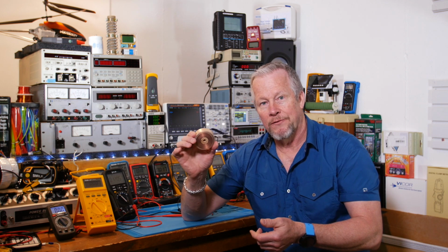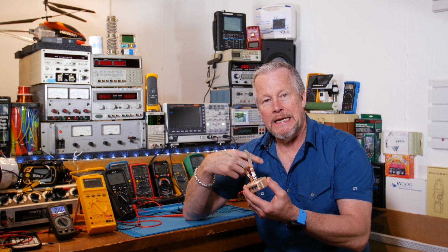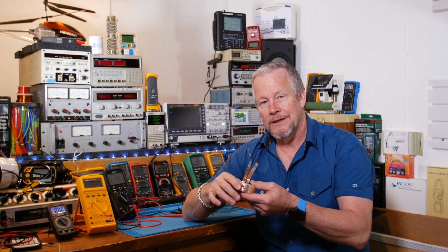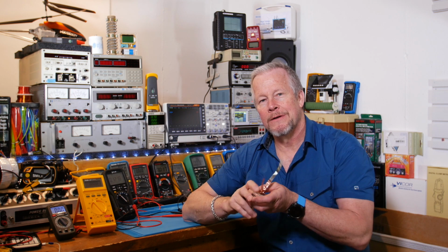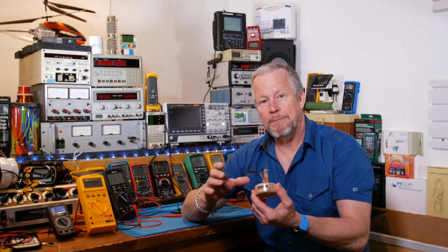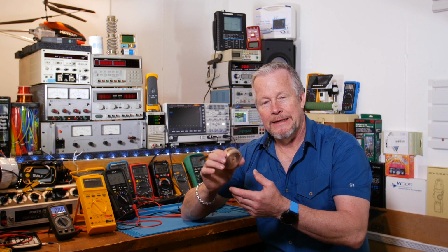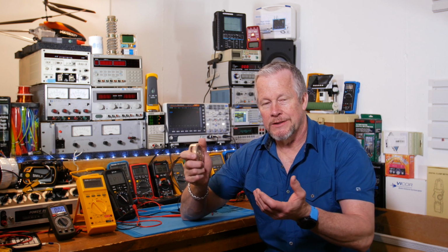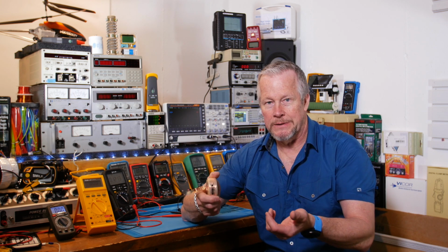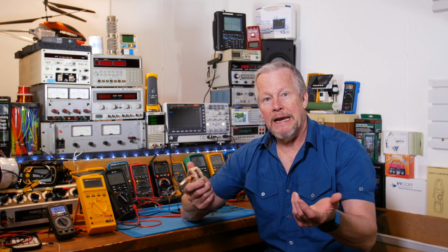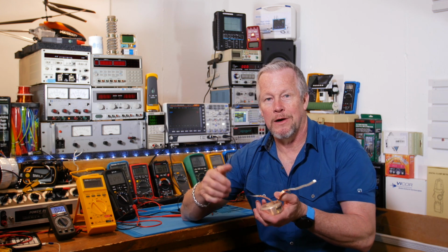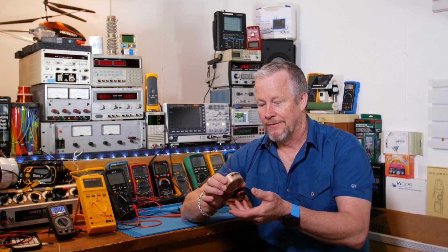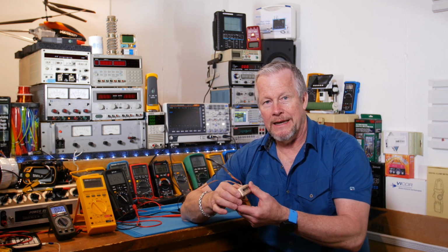Maybe you're going to modify an inductor like this, maybe take some turns off, and you want to check the impedance. And so we know that no part's perfect. They have parasitics, we call them. An inductor will also have some resistance, for instance. A capacitor will have some resistance. A resistor might have some inductance. So we like to get non-inductive resistors for our load banks and that, right? For audio type stuff at least. And even for power supplies.